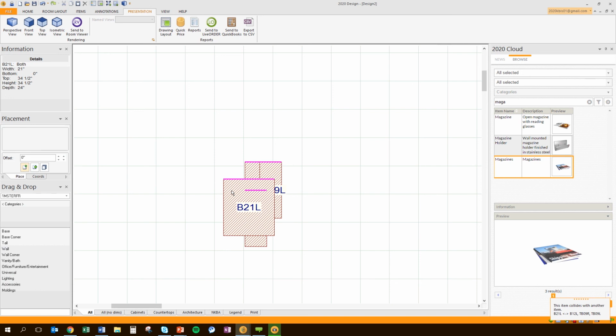And to give you an example of where the collision happened, it happened to me often when I'm trying to do switch item. When I'm using the switch item capability, certain manufacturers update their items, and the items are not necessarily the same width or height, which means the new replacing items now collide with older items. So now you'll be able to quickly mouse over each item and tell which item is colliding with what. So we see, again, a huge increase of productivity and efficiency by unlocking this feature for you.